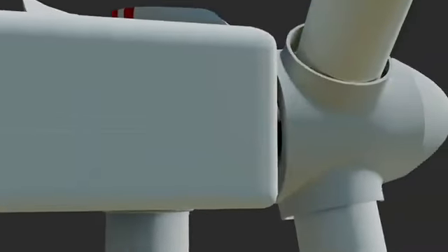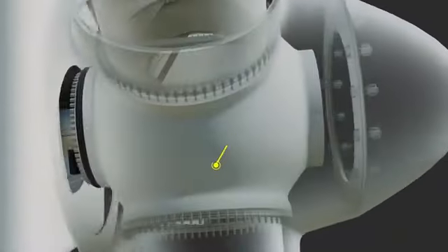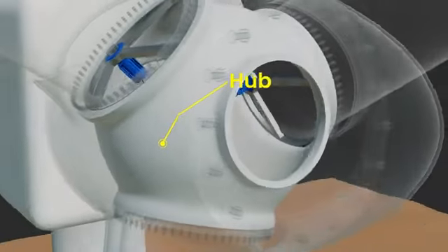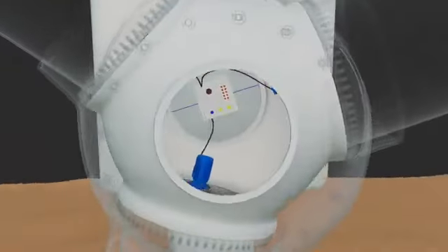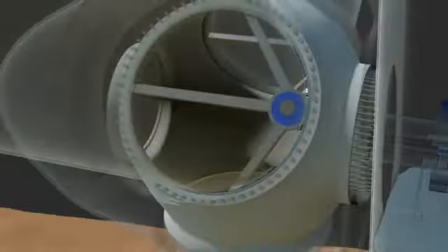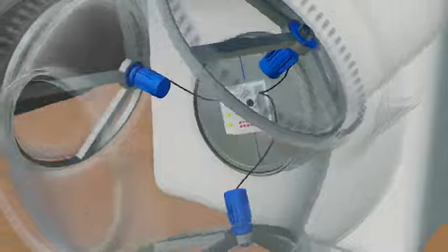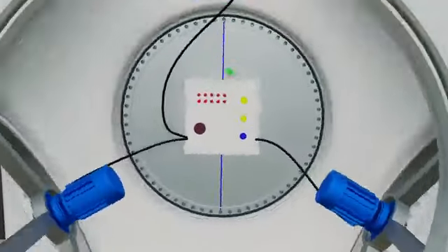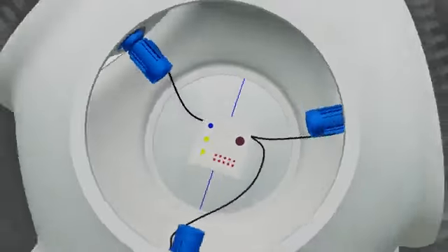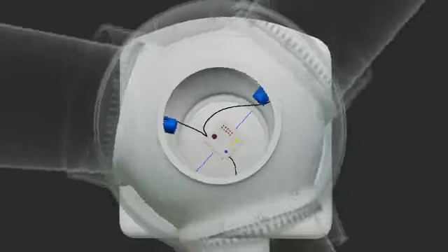The hub is not a simple shape. It is a complex, hollow 3D structure with 3 large, precision-angled openings for the blade bearings, 1 opening at the front, and 1 large opening at the back for the main shaft. The internal structure has walls and ribbing to direct the immense structural loads while leaving enough space for the pitch systems. The hub transfers the mechanical energy generated by the rotating blades to the main shaft.